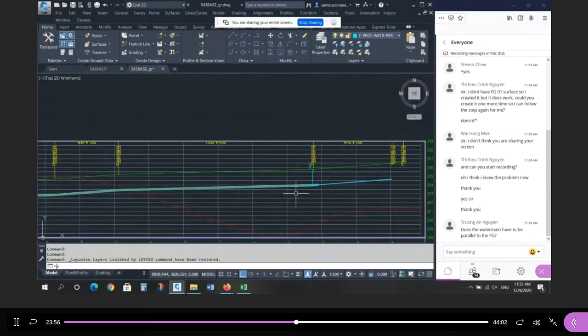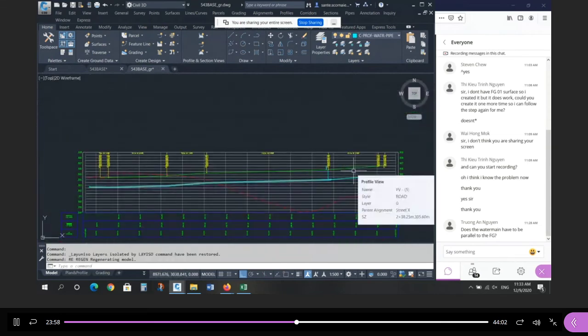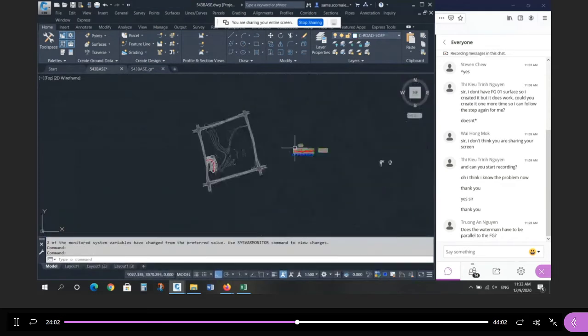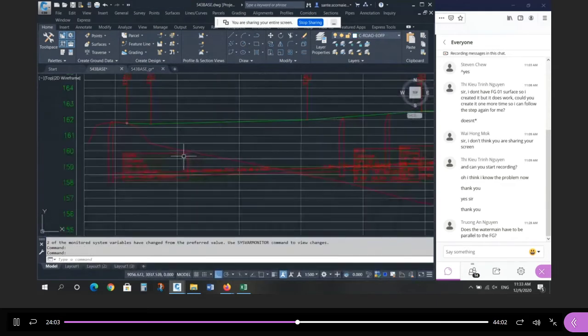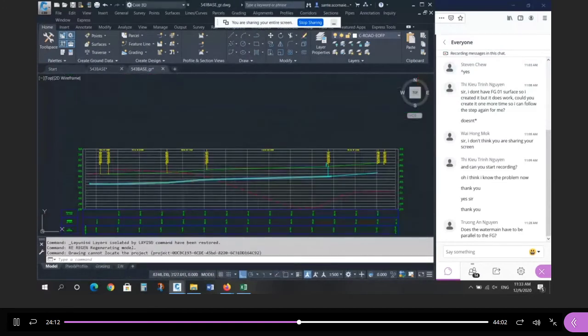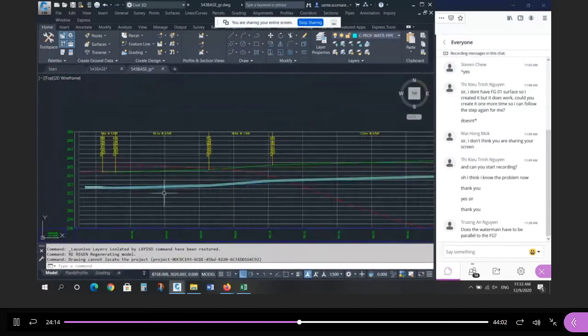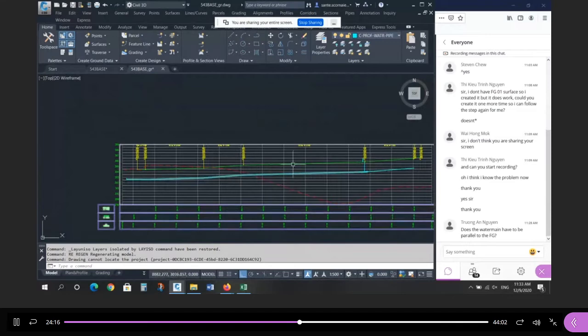Right? And then if everything is here with the pipes and so on, you have to deal with, if you're looking at this one, you have storm and sanitary pipes. The water main pipe is always above storm and san. Remember, this cover here is almost 3 meters. The pipe for the water main is going to be somewhere in between. And you'll see the water main. And then you have to label it. And then there'll be others, right?